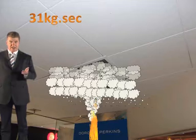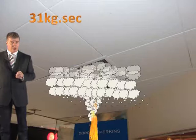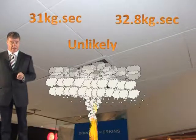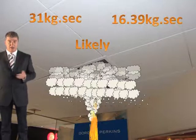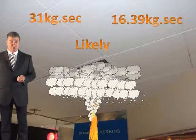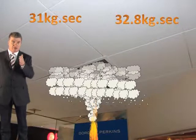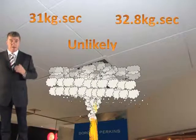That's it. So in this case, the smoke leaving each ventilator, we've said in the example, was 31 kilograms a second, and the mcrit is 16.39 kilograms a second, which means in this case it is very likely that plug holing will occur. So you will get air entrained in, and you need to do something about it. One possible method is having more, smaller vents in each reservoir, but as it stands it will plug hole.